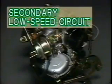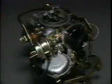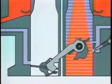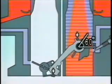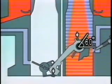Let's look at the low-speed circuit for the secondary barrel. If the primary throttle valve opens more than 60 degrees, the cam in the kick-up system will force the secondary throttle valve to open slightly. This uncovers the secondary slow port, causing fuel to be delivered to the intake manifold.